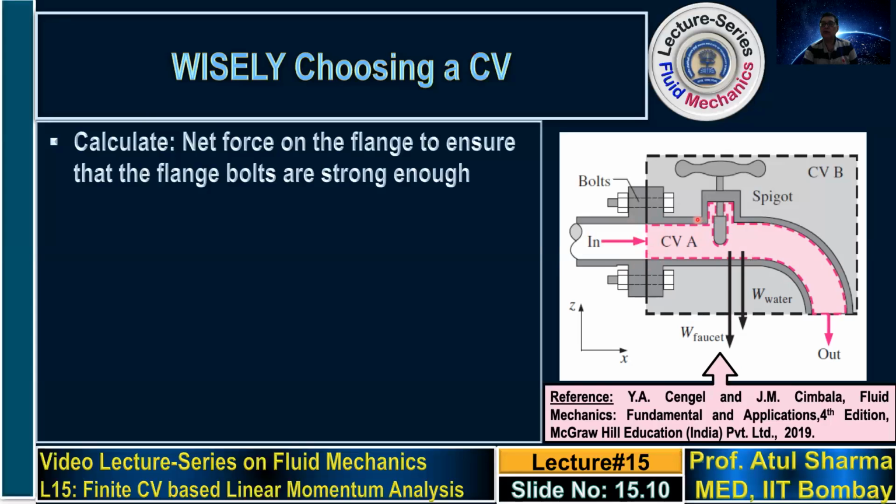But the issue is, if you see the other surfaces like this black control volume, as far as the surface force is concerned, assuming the ambient condition has no velocity gradient, at this black dotted line based control surface the only surface force acting is the pressure force, and the pressure is atmospheric everywhere.